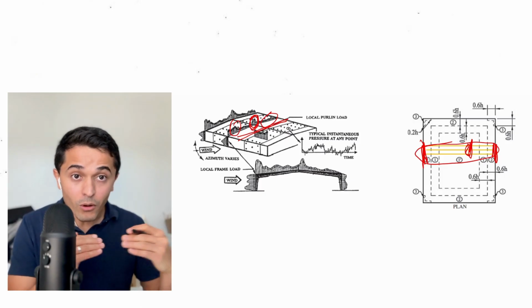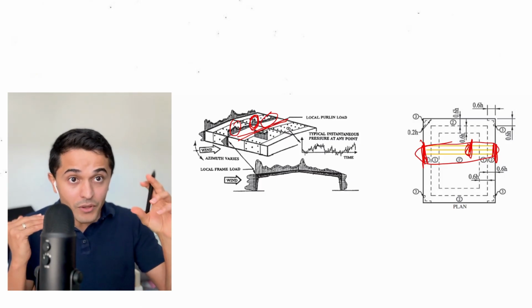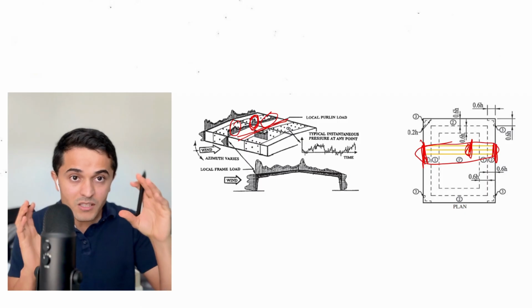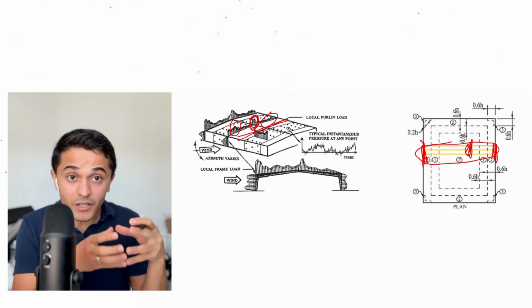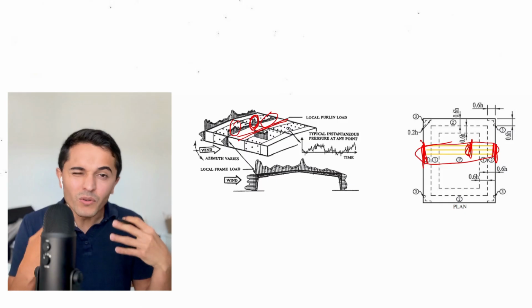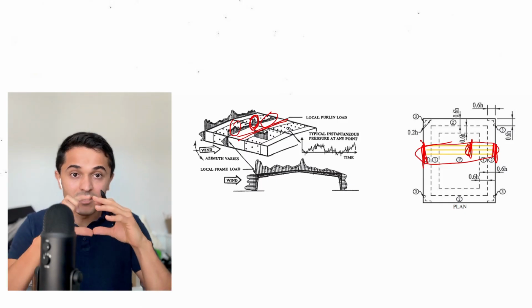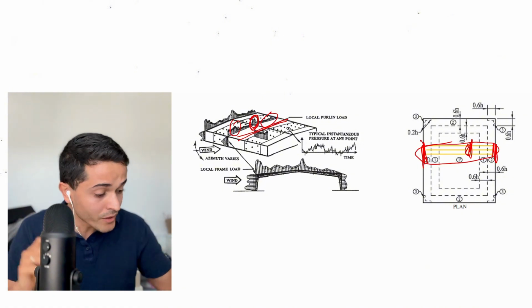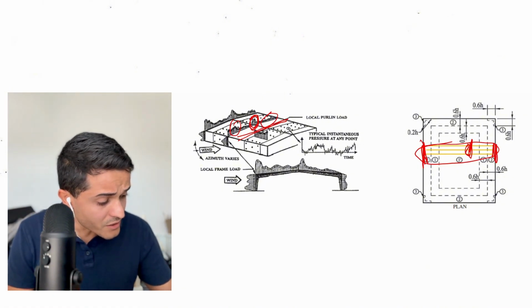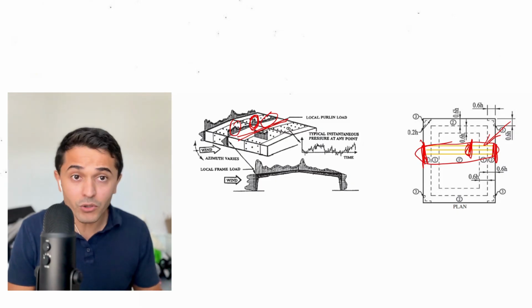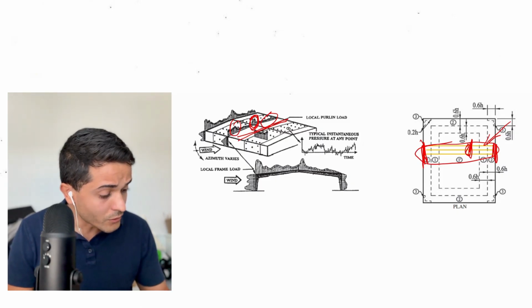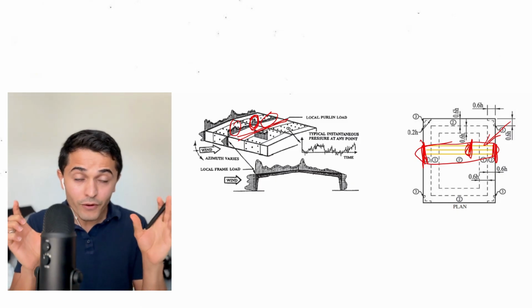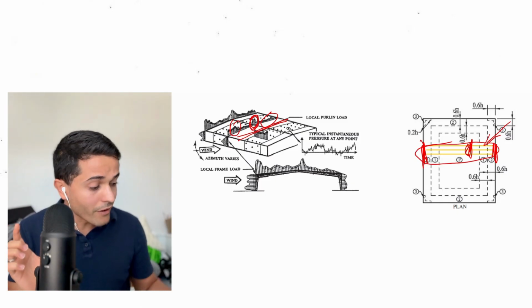Basically, if you have a long spanning member, even though that member may see a hotspot, those hotspots are smaller in nature, therefore you don't need to be penalized in designing that entire member for that hotspot pressure, per se. So for this specific truss, you'd have zones 1 prime, zone 1, and zone 2 that you would need to find the equivalent GCP value for.